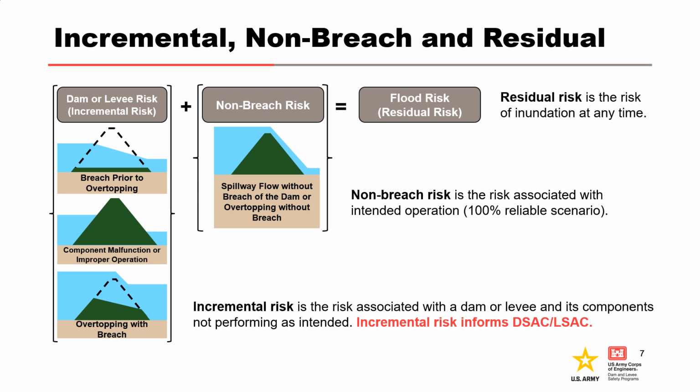Residual risk is also known as the flood risk and refers to the total risk of inundation within the floodplain, and for dams includes the reservoir area. While we calculate and discuss all three with decision makers, the Dam Safety Action Classification or DSAC and the Levee Safety Action Classification or LSAC, which are used to prioritize the inventory, are informed only by the incremental risk, the risk associated with the structure.